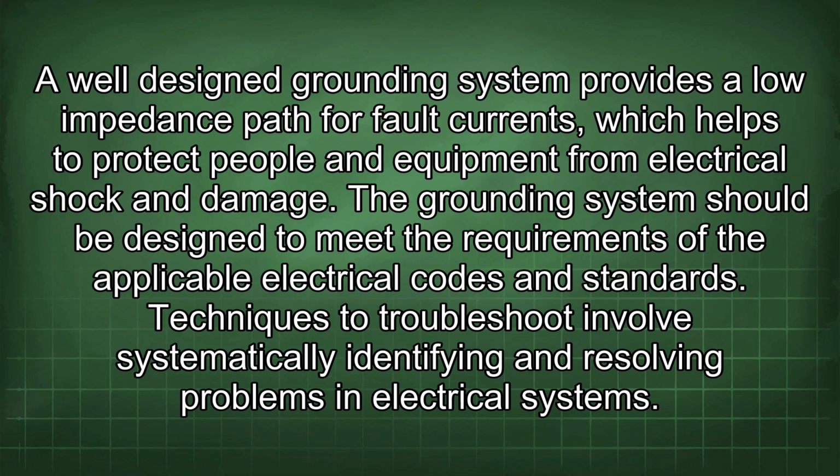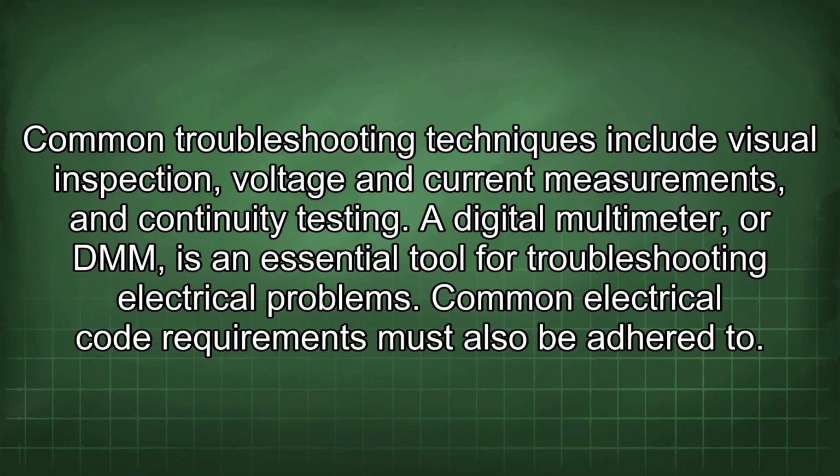Techniques to troubleshoot involve systematically identifying and resolving problems in electrical systems. Common troubleshooting techniques include visual inspection, voltage and current measurements, and continuity testing. A digital multimeter, or DMM, is an essential tool for troubleshooting electrical problems.